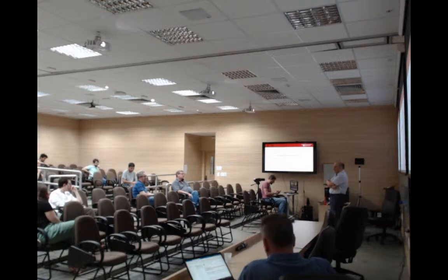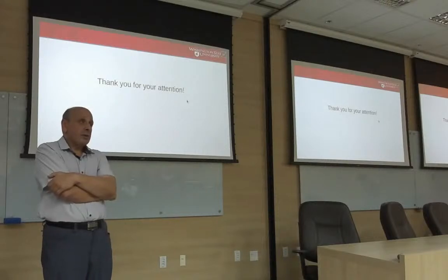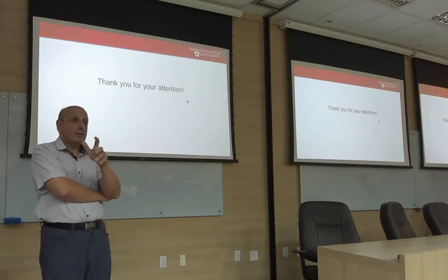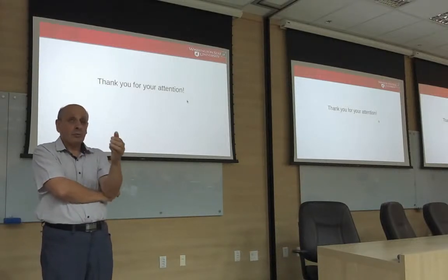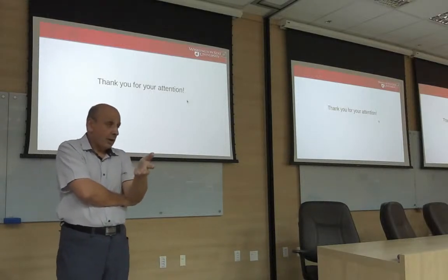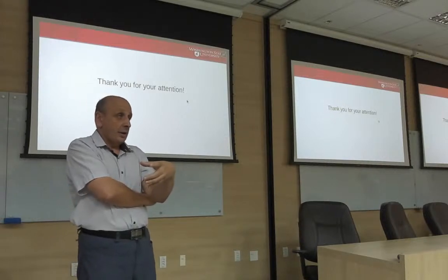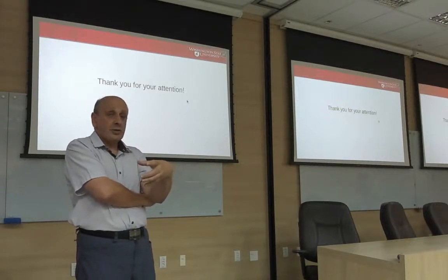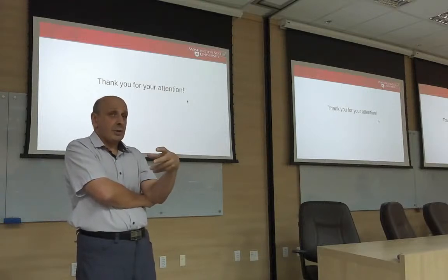With the new chip, they have microcode on which they've written two or three slightly different neurons, and several research groups have expanded with a few more neurons. So, for example, one of the exciting new neurons available there, I think well validated, is the Izhikevich neuron, which is a 3-state neuron with a lot of nonlinear dynamics.